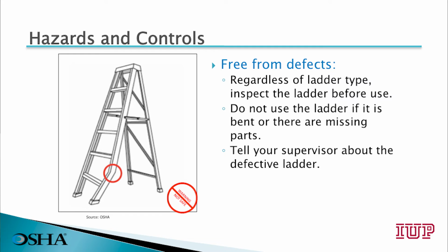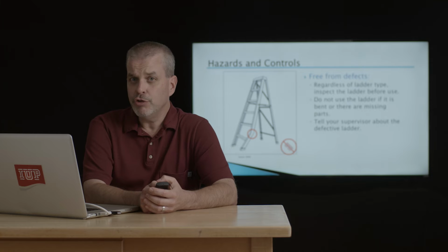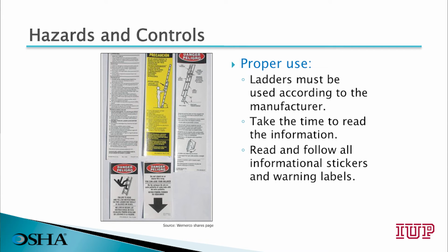Ensure your ladder is free from defects. Regardless of the type of ladder you use, you need to inspect that ladder before each use. Do not use the ladder if it's bent, broken, or if there are missing parts, and tell your supervisor about the defective ladder. Proper use includes using the ladder in accordance with the manufacturer's requirements.